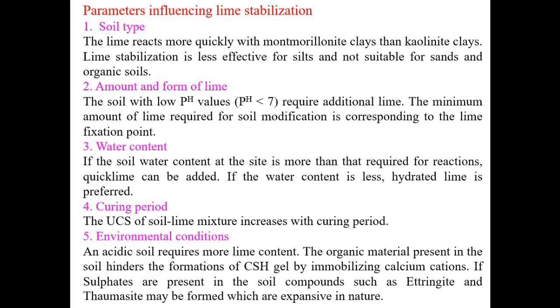The last parameter is environmental conditions. An acidic soil requires more lime content. The organic material present in the soil hinders the formation of calcium silicate hydrate gel by immobilizing calcium cations.